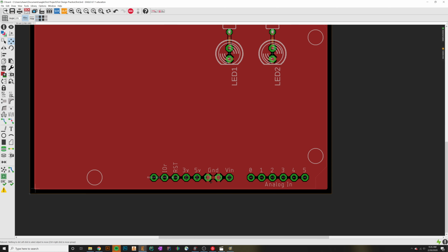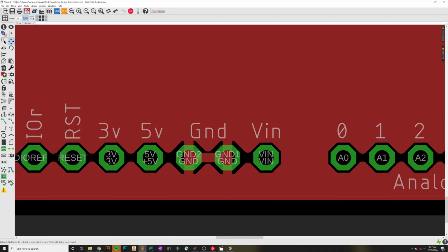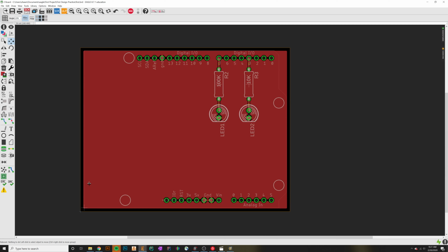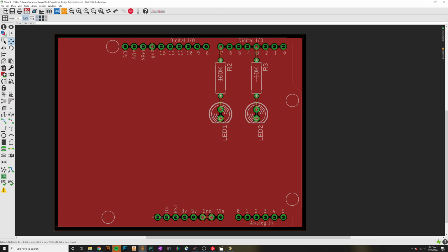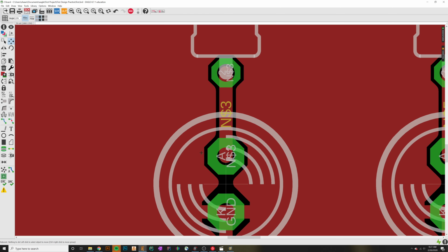Now what the ground plane did was it simply opened up a section of the little copper pad that was there and connected it to this large copper plane that now sits on the top of this board. You can see in the regions where the copper plane is not supposed to connect to a trace, there is this distinct outline surrounding it.